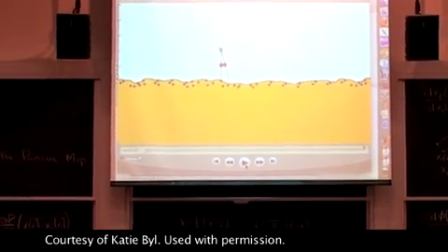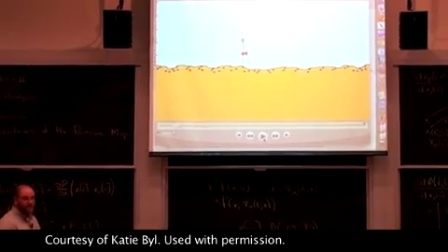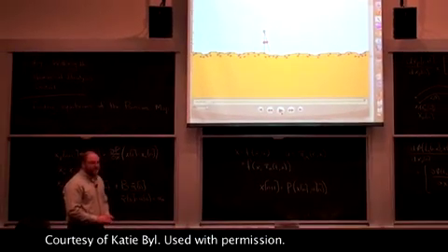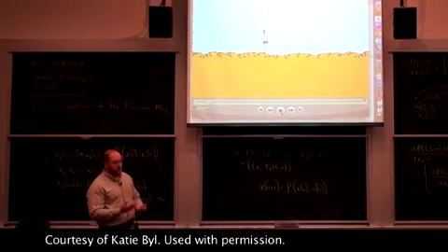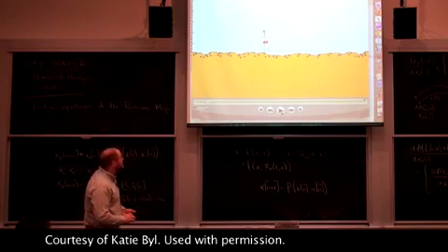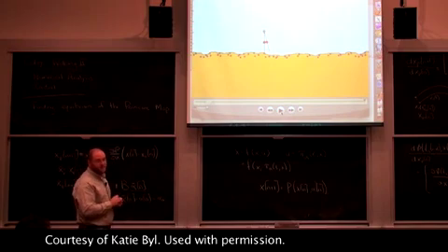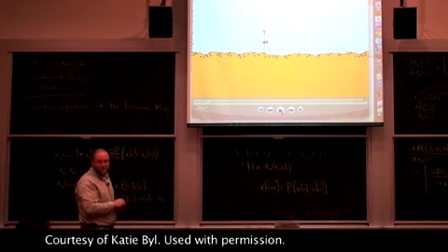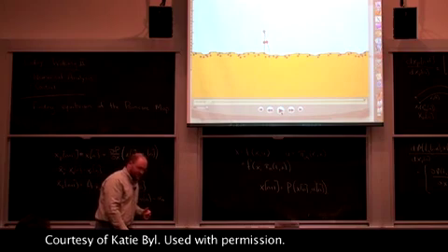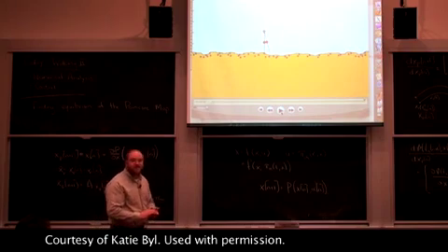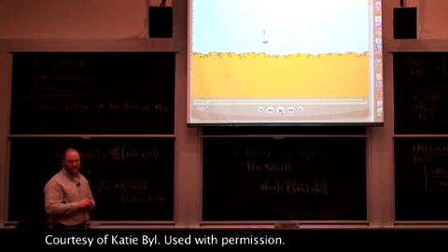Does it have the exact terrain? It does, yeah. The slope of the terrain? It doesn't think about the slope of the terrain. It could. But the reason it's tractable, if you can tell by the foot points, it wraps around. So we've got a limited state space in X. Doesn't worry about the swing foot hitting the ground? We ignore that. If you look real carefully, I think the leg gets a little shorter every time it goes, right? But it's a massless leg, so there's no dynamics like that.